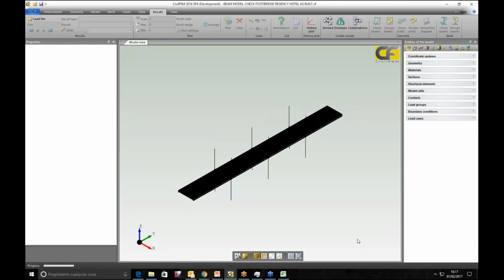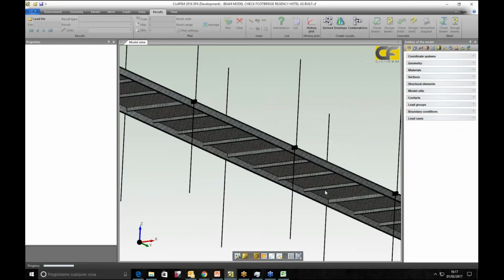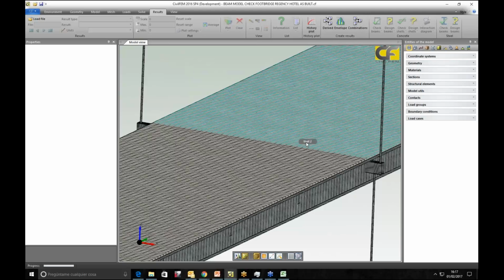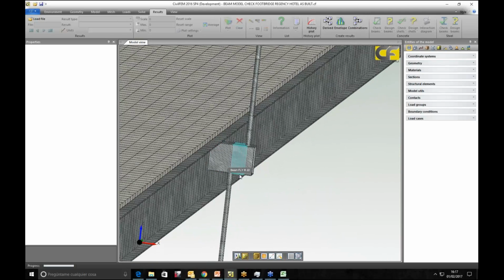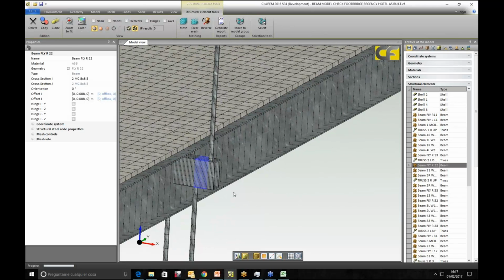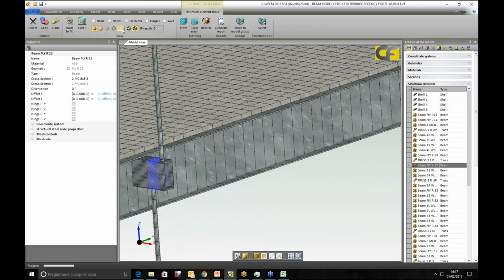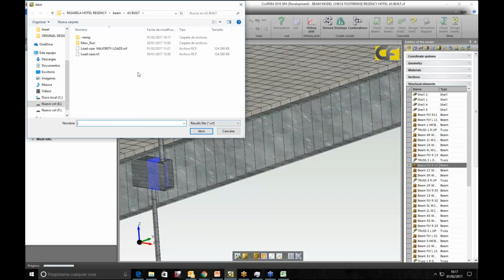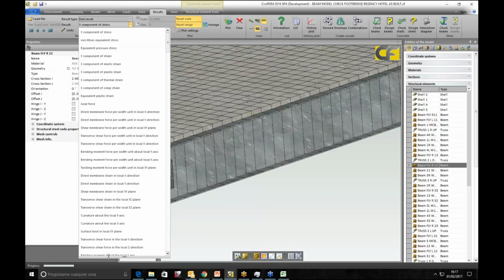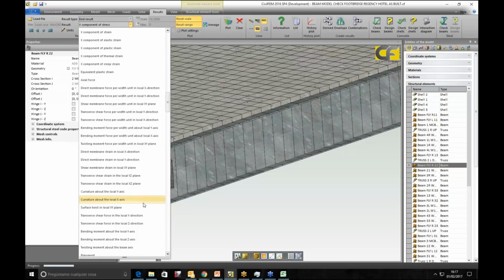Here, just watching it, it's exactly the same model, but we can see that instead of having a continuous line of hangers, they are divided into one side and the other. So in this part, we will have the biggest stress problems. There was a structural change in the structure, and we will see what the consequence of that is. First, the value we are plotting is the shear force that we saw, that's the most unfavorable load force on the model.